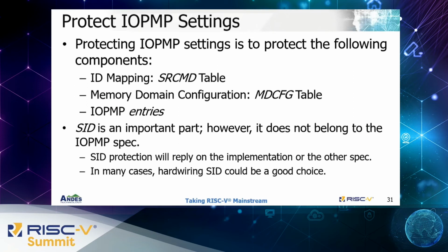Even though SIDs are very important for an IOPMP-based system, they don't belong to the IOPMP itself. Their protection involves the bus master's design. In the current stage, SID protection is implementation dependent. In many cases, it even can be hardwired. If it is not, allow the change only at boot time unless you have another protection mechanism.